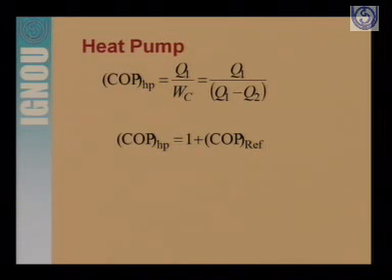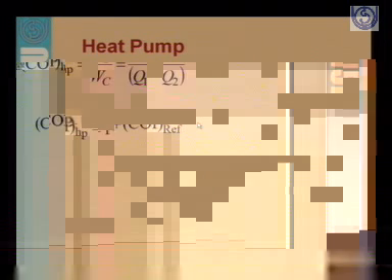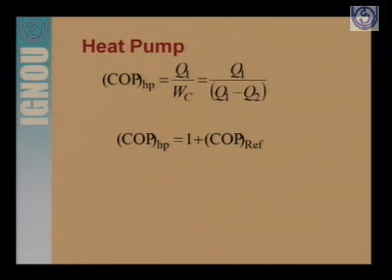One very important device is there, we call it heat pump. So heat pump is basically pumping heat to the system, and that is defined as Q1 by WC, and if we do a little algebra then we can find out the coefficient of heat pump will be equal to 1 plus coefficient of refrigerator.